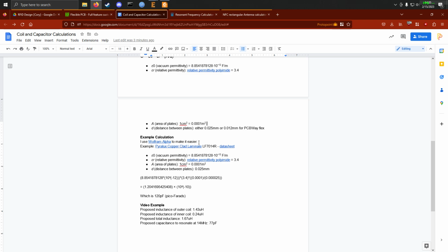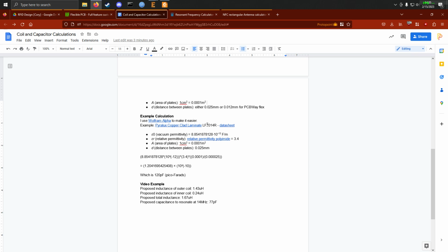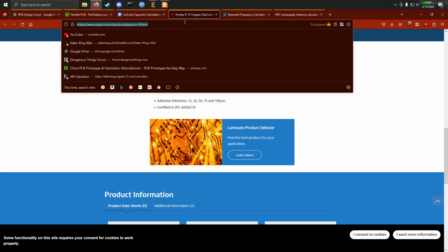So an example I used here, you're talking about using copper foil tape. I looked on 3M, the manufacturer's website, for copper foil tape, and a lot of those were for EMI shielding. So they're a copper foil with a conductive adhesive on both sides. They're not really two plates separated by a separator, so they're not really ideal for emulating this behavior. I recommend you attempt to get some Pyralux, that's what they call this stuff. Copper clad laminate. That's not actually a picture here.